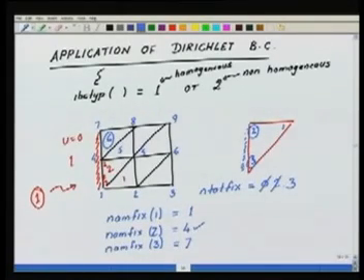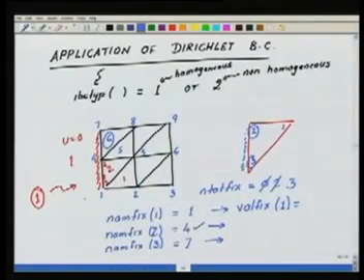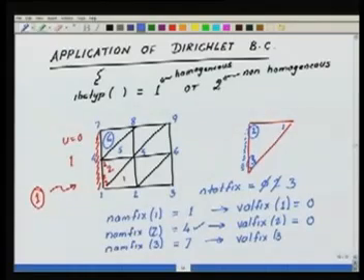So I know that there are 3 degrees of freedom which have to be fixed coming out of the Dirichlet boundary conditions, and I know the names of these degrees of freedom. While I am naming them, at the same time I look at the type, so I can find the value of the fixed degree of freedom. You need not have only 0 boundary conditions. You can have a fixed displacement or a fixed temperature which is non-zero on the edge. So the value of the first fixed degree of freedom comes from the information given for this boundary edge, in this case 0. Similarly, the value for the second fixed degree of freedom is also 0, and for the third is also 0.